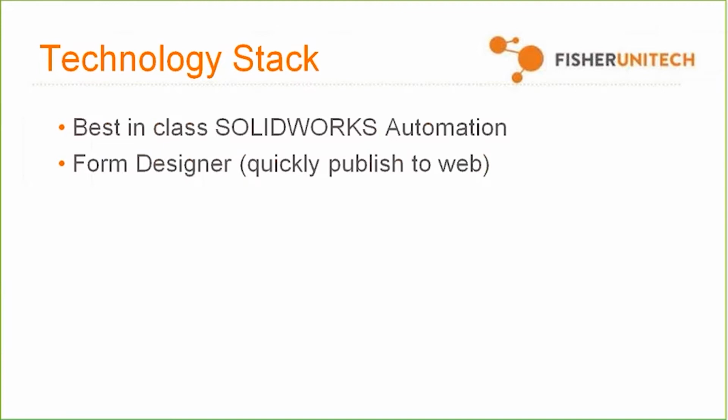So if any of you have ever used the custom property tab builder within SolidWorks, it's somewhat similar to that. You're able to design an input form. That input form can then be connected to variables and other kinds of information, and then those variables and form controls can be connected to real data within SolidWorks, whether it be a dimension or a feature. Also, you can take this form and publish it easily to the internet, which is something that we're going to see later, so that if you wanted your customers to automatically specify products, they'd be able to do that.